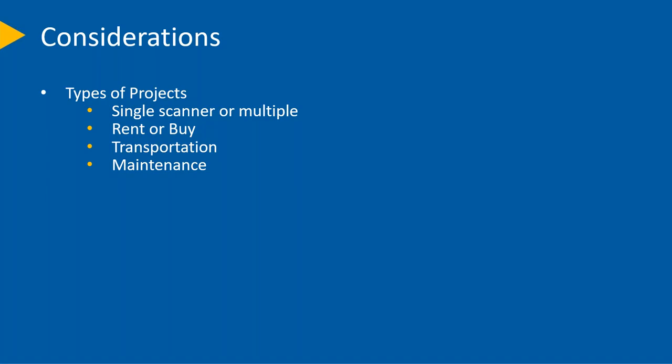You can have single scanners, you can have multiple scanners. Many times the guys here at Trimble will go out and do historical preservation for different groups, and we'll take multiple scanners out to capture the project faster and get it done. We'll take different types of scanners even. We'll take big scanners and little scanners, short range and long range, based on what we need to do to get it done. And then we want to bring it all back together into a single software, either Trimble RealWorks or Trimble Business Center on our side.